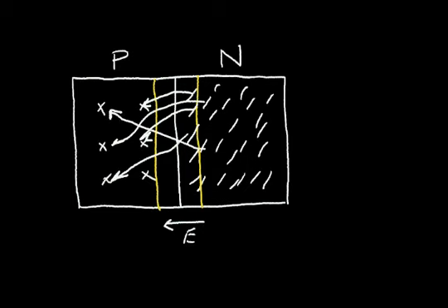to recombine. So what happens is, because the P region is lightly doped, the depletion region extends further into the region that is lightly doped, where the concentration is smaller. And at the junction, the depletion region is smaller into the N region, where the concentration of carriers is higher. So let me erase this. Let's redraw this p-n junction region.